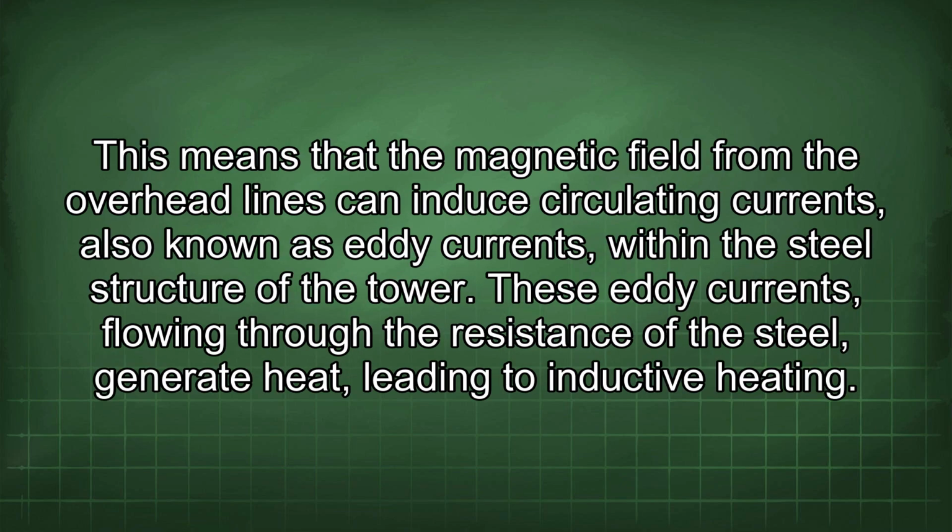This means that the magnetic field from the overhead lines can induce circulating currents, also known as eddy currents, within the steel structure of the tower. These eddy currents, flowing through the resistance of the steel, generate heat, leading to inductive heating.